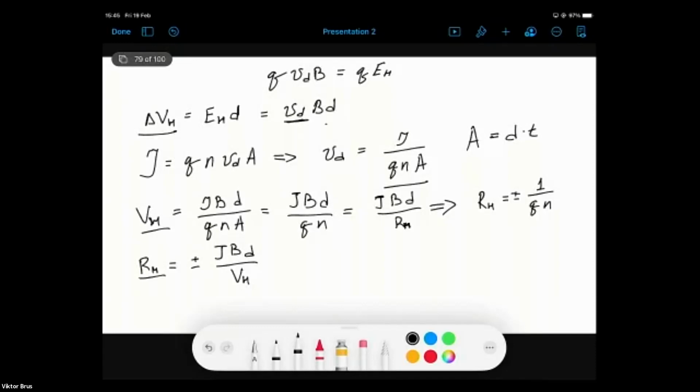If that is true, then we know the experimentally measured value of the Hall coefficient. And we also know that this Hall coefficient is either positive or negative, which tells us already about the majority charge carriers, their type, electrons or holes, and the type of semiconductor we deal with, electron type or hole type semiconductor. And this is equal to plus minus Q divided by N, which is the concentration of these charge carriers.